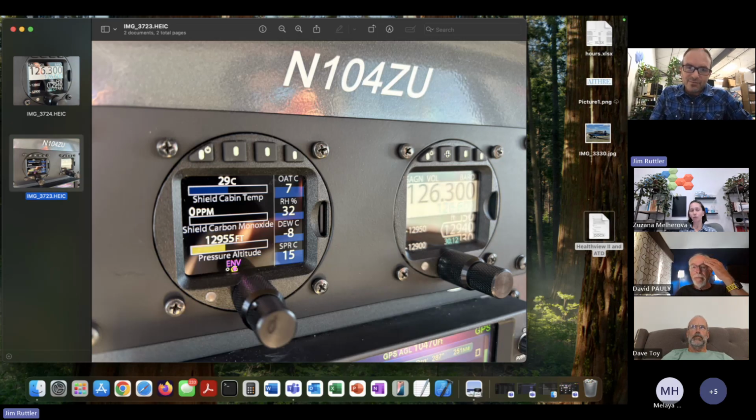And on top of all that, you can see the barometric pressure altimeter. This is actually hooked up to my static port in the aircraft, and it is a third backup pressure altimeter indication, which is really clear, and I like that feature too. So the air portfolio includes the HealthView, the transponder and the radio, the altimeter, and then the ADSB traffic and weather, all using the same control heads.